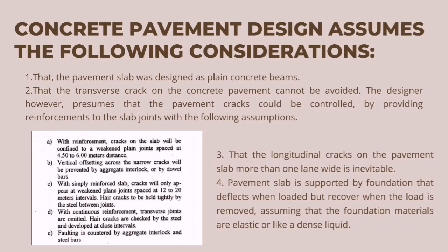Concrete pavement design assumes the following considerations. First, that the pavement slab was designed as plain concrete beams. Second, that the transverse cracks on the concrete pavement cannot be avoided. The designer, however, presumes that the pavement cracks could be controlled by providing reinforcements to the slab joints with the following assumptions.